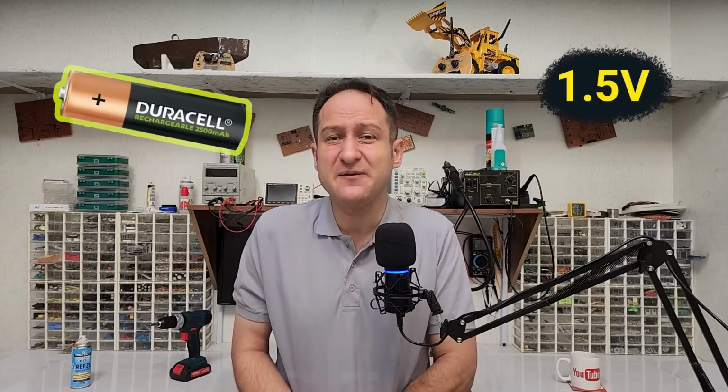Since a BJT will be turned on with a base voltage above 0.7 volts, you will be comfortable using a BJT when the circuit is operating on these AA batteries, because most MOSFETs are triggered by a gate-source voltage higher than 4 volts. I know there are some FET transistors that have a gate-source threshold value lower than 1 volt, but the number of them is not much.